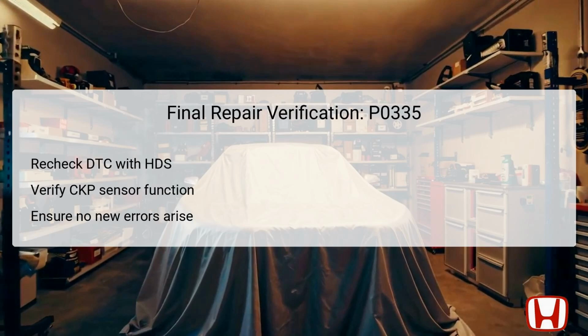After performing the necessary repairs, our next step involves conducting a final verification of the results. Using the HDS, we will recheck for any DTCs to ensure that DTC P0335 does not reappear. Additionally, it's essential to verify that the CKP sensor is functioning correctly by monitoring its readings during operation. This verification not only confirms that the issue has been resolved, but also checks for any other potential error codes that might have emerged during testing.